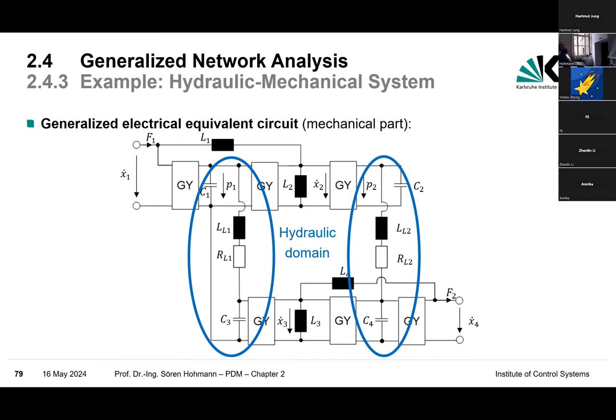This means I have a linear relation for inductance, a linear relation for a resistor, a linear relation for a capacitor, and also for gyrators and transformers, etc. So if we glue this together, we can derive all sides so that at the very end, all derivatives disappear. Every integral can be differentiated once, then you get just an algebraic relation.